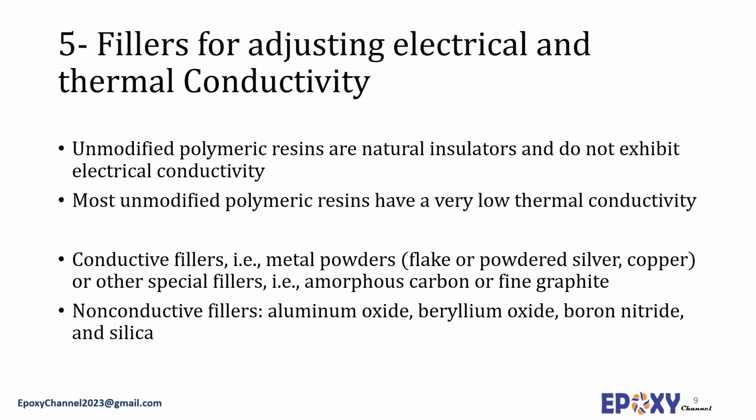Increased electrical or thermal conductivity is generally accomplished by adding conductive fillers to the epoxy formulations. For optimum electrical or thermal conductivity, the particles must be so concentrated that they come into contact with one another, which requires such a high level of filler loading that other properties may be significantly degraded. Appropriate fillers have been used to produce epoxy systems with high electrical conductivity.